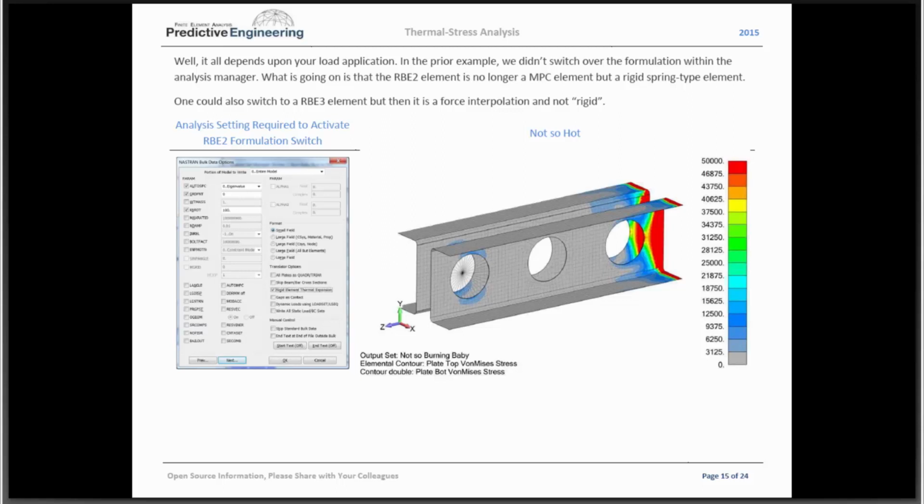So rather than going 70 to 200, I would just focus on the delta. So I'd start at 0 and go up to 130. So I have the same temperature delta, but you start at 0 to accommodate those rigid elements. That's a good point. Yeah, I forgot about that, because you don't get to pick a reference temperature for those.